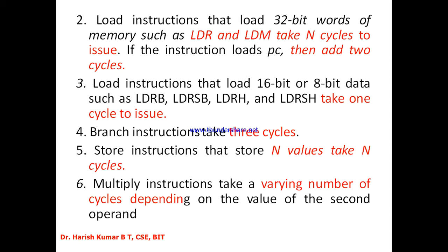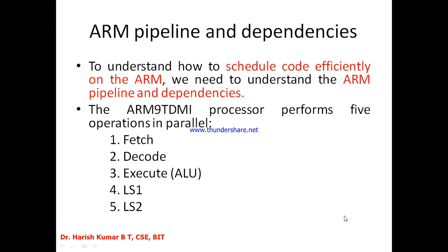So how long it is, whether it is a byte, or a half word, or a full word. This is what you know, because the multiply instruction takes more than one execution cycle, and there is no fixed number of cycles for this, because it depends on the length of the second argument.